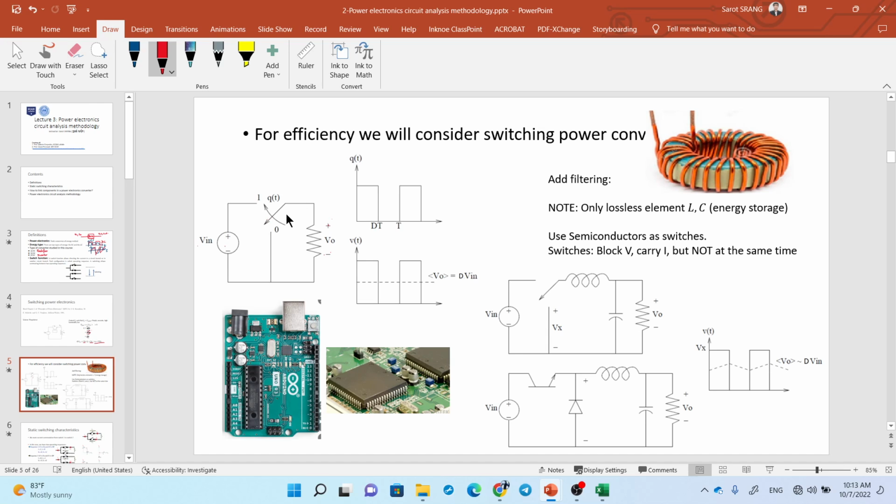But it doesn't mean the input spends the full power and the output receives half. It doesn't mean that. I mean the input itself releases only 50% and the output receives almost 50%. So actually for this kind of switching function used in power electronics, you can achieve efficiency up to 95%, 98%, compared to 66.66%. See, you save a lot of energy.